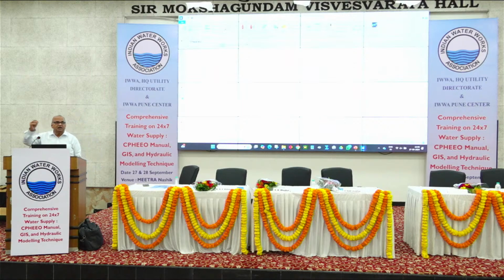Now the next step which madam has told is, first of all, make it a rule. Rule number 8, your units. While preparing the hydraulic model of Badlapur and Ambernath, I was just a novice and new learner, so our unit was in FPS. After so many efforts, still the model was wrong because of this silly mistake. Since then, I made a rule: before touching further, we must check the units of the hydraulic model correctly.